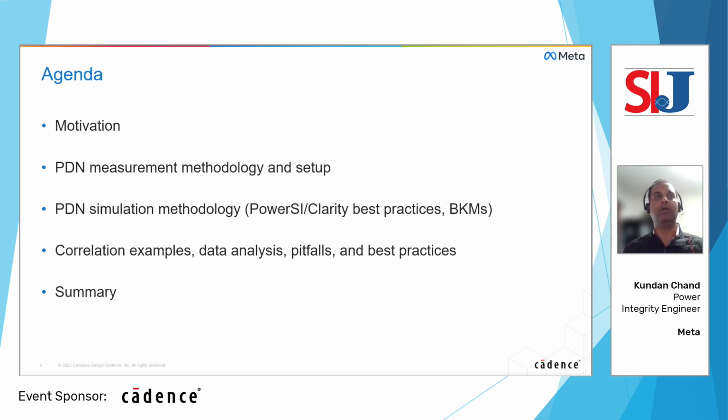After that, we go over the PDN simulations methodology and what are the different knobs and settings we used for the hybrid solver as well as the 3D full wave solver, and go over the different best known methods we should be using for correlation. And then followed by the various correlation examples and plots, how good we are able to do the correlation and the best practices, and followed by the summary for this work, which we did.